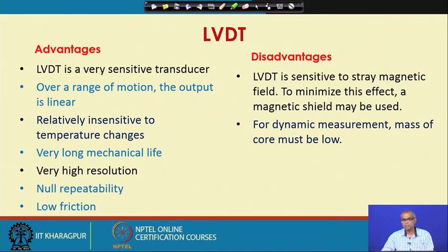As explained earlier, LVDT may be sensitive to stray magnetic field. To minimize this effect of outside magnetic field or stray magnetic field, a magnetic shield may be used.